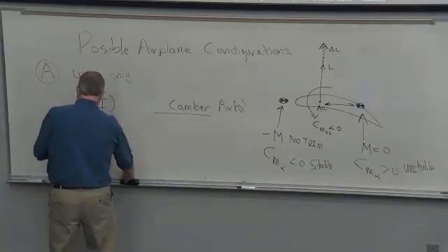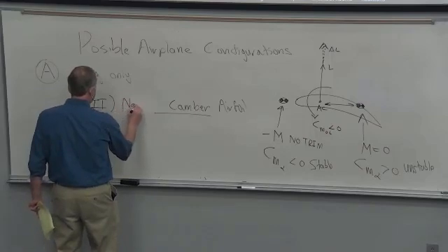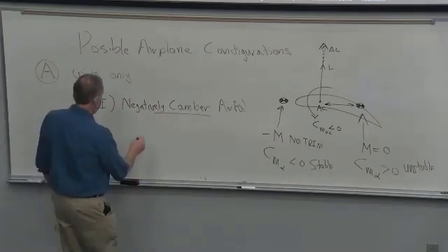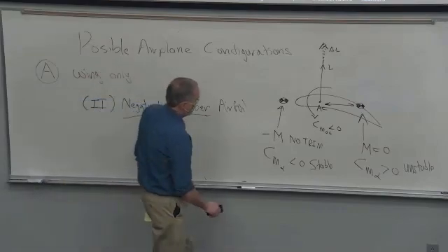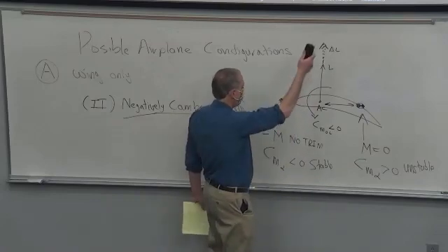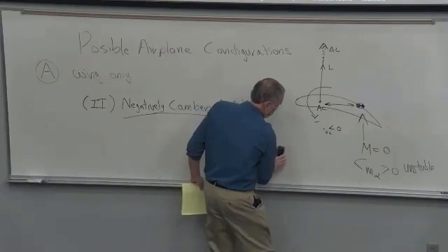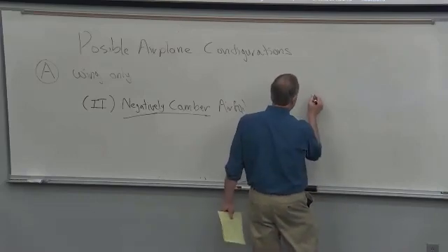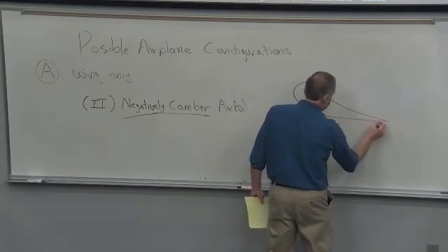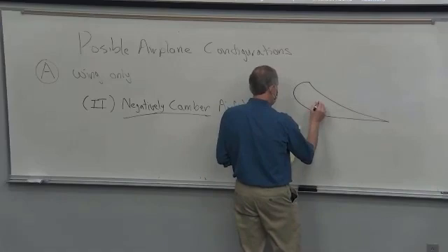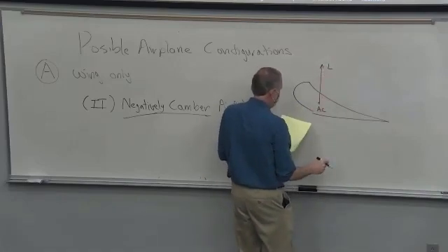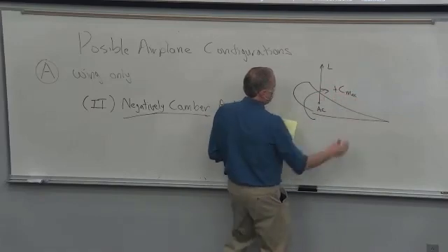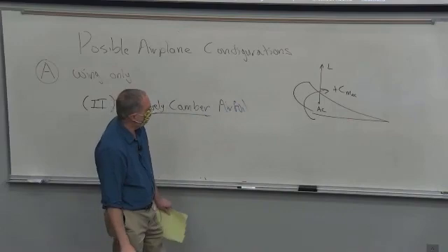All right, so how about a negatively cambered airfoil? In other words, we're going to flip it upside down. So we flip it around. If we tilt it enough, we're going to get lift up, and it's going to flip the pitching moment. So here's what we've got now. Got an airfoil that looks like that. Here's the aerodynamic center. And if we tilt it up enough, we can get lift like that. And we've got a positive pitching moment just because of the pressure distribution of this thing.